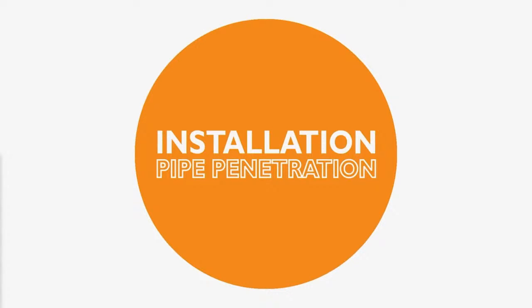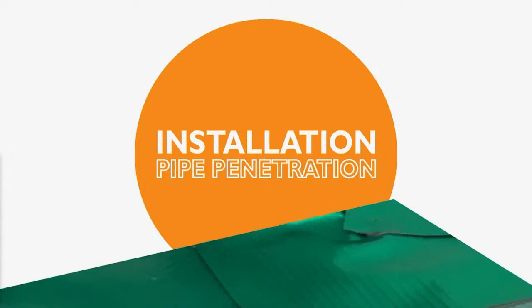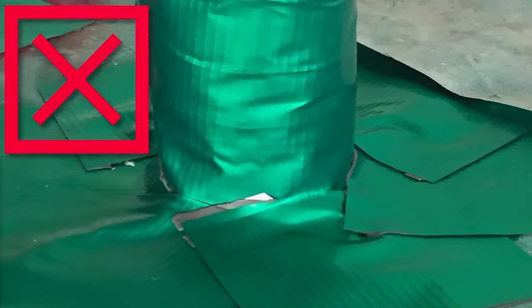Pipe penetrations are another area it's important to get right, as they are a common feature on many sites. These are images shown of the more common problems that can occur. In the first case, the supply top hats did not fit properly, so the installers have got a little creative. While it's possible this detail may work to provide a gas-tight seal, it's by no means a given and would almost be impossible to verify.